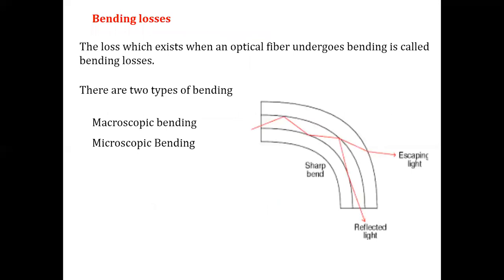bending losses. So bending losses are due to curvature and losses caused by an abrupt change in the radius of the curvature are referred to be bending losses. Here we have the sharp bend of the fiber, right? So the sharp bend of the fiber causes significant radiative losses, and there is also a possibility of mechanical failure. Right? So these type of losses are represented as bending loss.